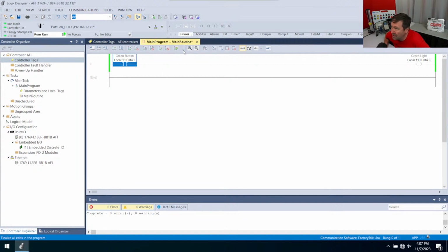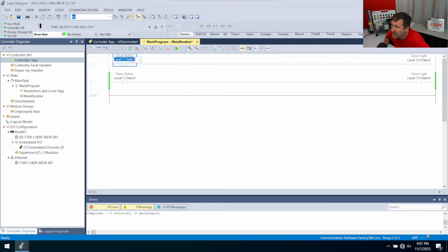So that makes a nice automated package if you know that you want to do it and you don't want an undo button. All right, now let's go through this again and talk about how we ended up in that whole discussion the other week. So I'm going to start a rung edit, and I'm going to change this back to the yellow light. And I'm going to accept it, and I'm going to test it.